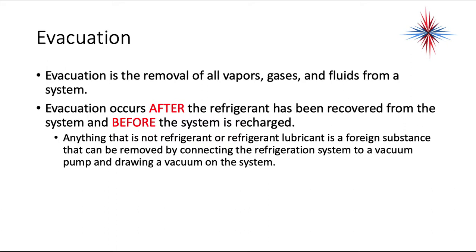Evacuation occurs after the refrigerant has been recovered from the system and before the system is recharged. Anything that is not refrigerant or refrigerant lubricant is a foreign substance that can be removed by connecting the refrigeration system to a vacuum pump and drawing a vacuum on the system.